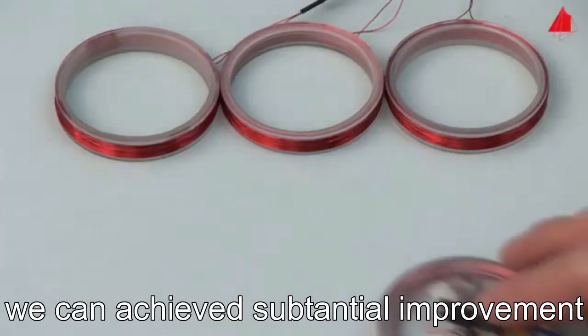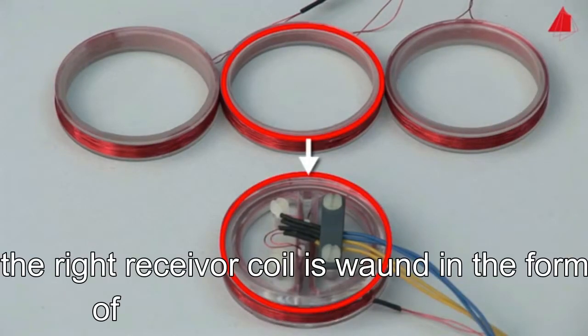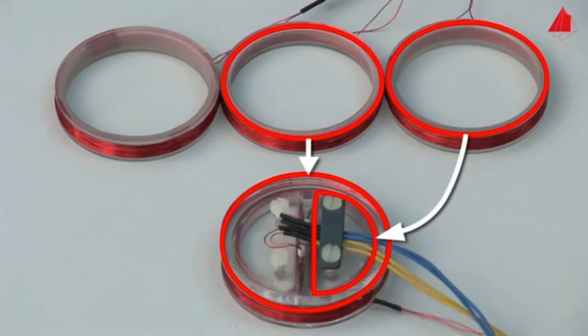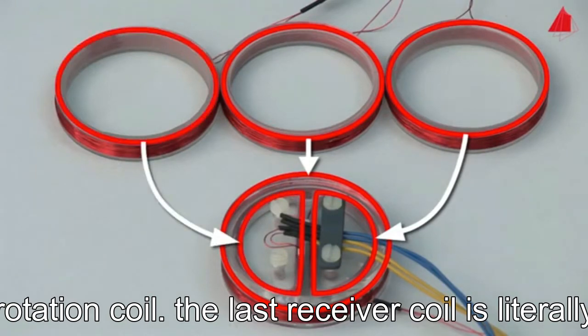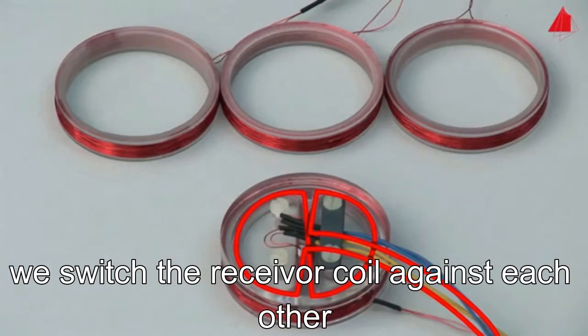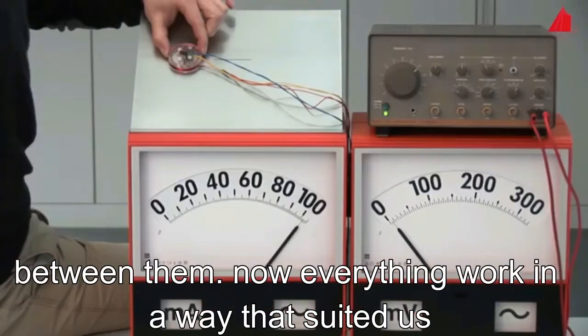We can achieve a substantial improvement with this layout of coils. The excitation coil remains unchanged. The right receiver coil is wound in the form of a capital D and sits within the excitation coil. The left receiver coil is laterally inverted. We switch the receiver coils against each other and only measure the voltage difference between them. Now everything works in a way that suits us.